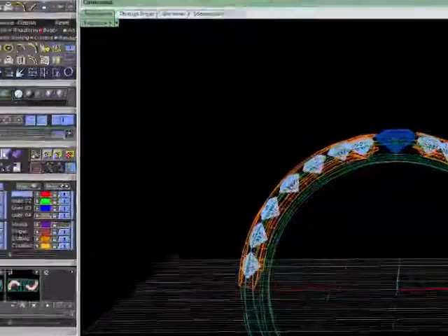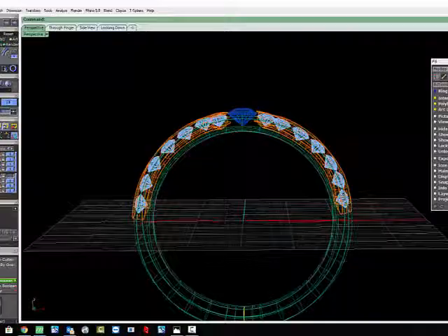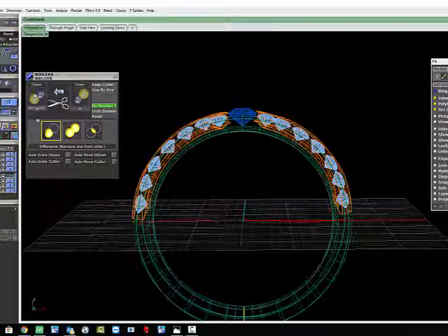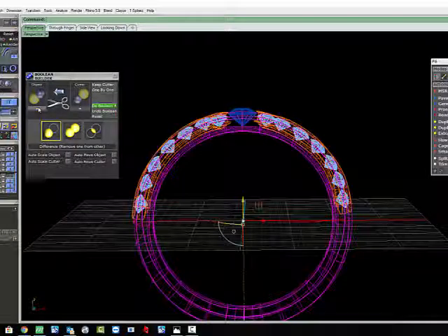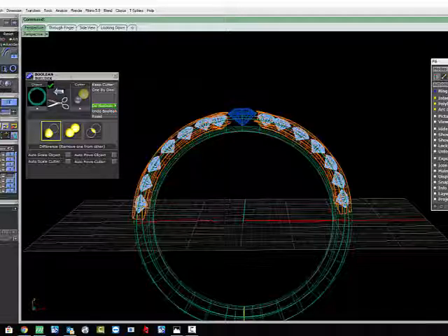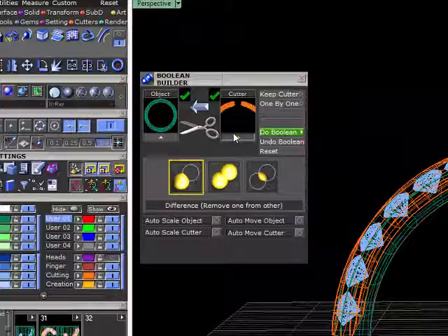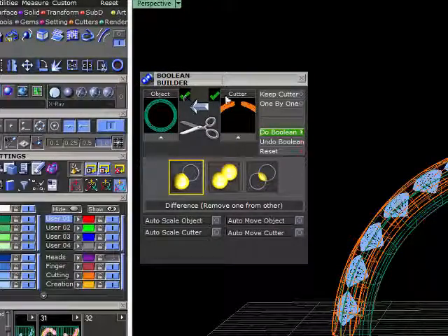We're now going to go to the Boolean method under Tools. It's the two balls here on the bottom page. Two balls is the logo we use. The object will always be the metal or the shank that you're going to use. So drop it into the box by hitting the triangle. The cutters, well, we know what the cutters are. Is that orange part and that orange part, or you just right click on the actual color itself and drop it in there, and it says nice big tick, the model's okay. If the model was not solid, it would be a cross. I want a difference, so I want to cut one from t'other, do Boolean.